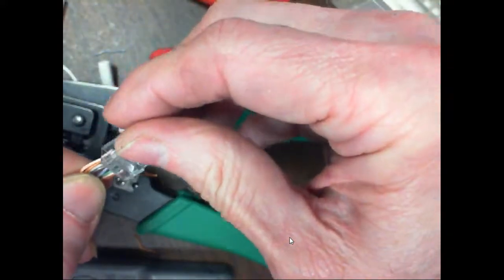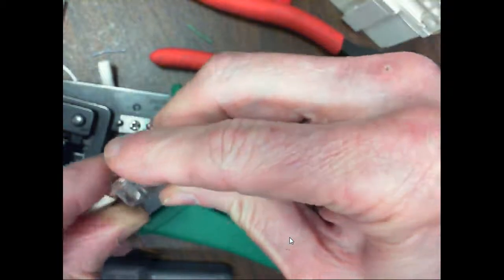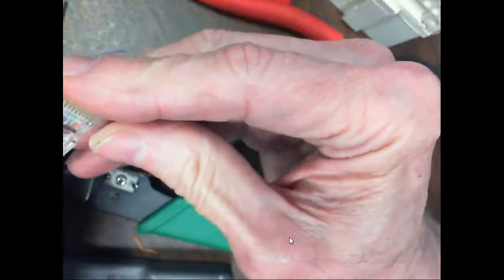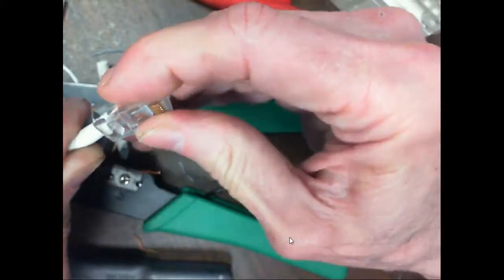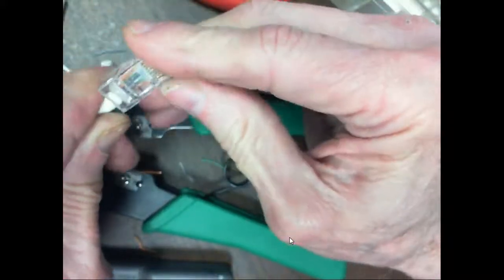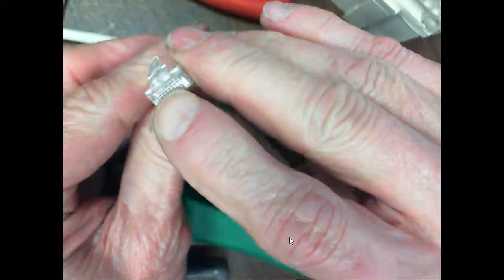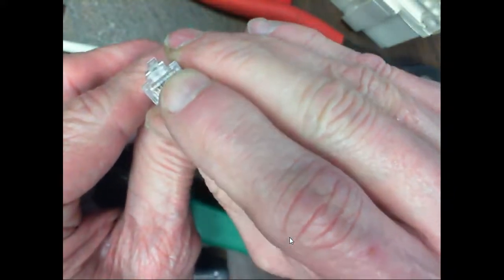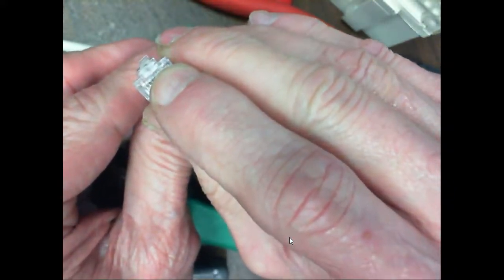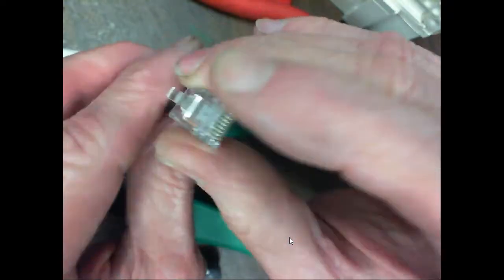That's okay. This is a demonstration anyway. I'm going to slide it in there, right? You understand? I'm going to push that jacket until it gets under that crimp, right? You understand that? I'm going to come up here and look at the front. What I'm looking for is these little old copper circles right here, which indicates I've got the wires all the way up to the end.